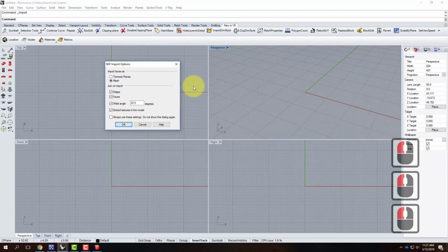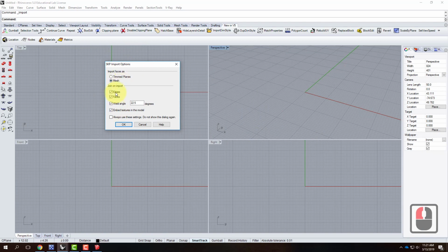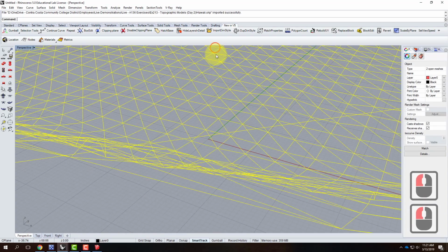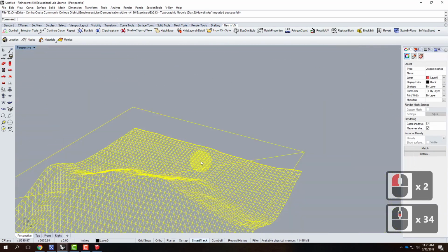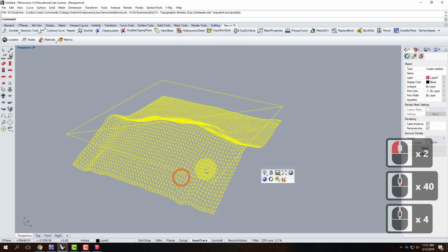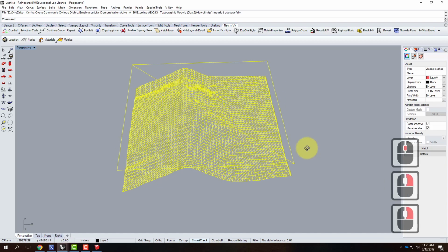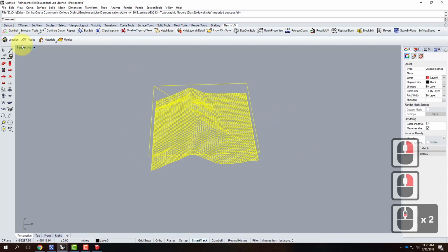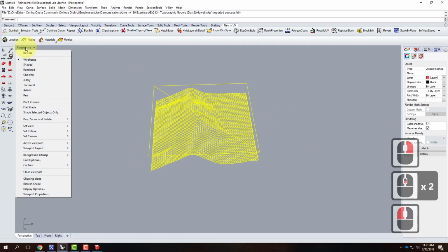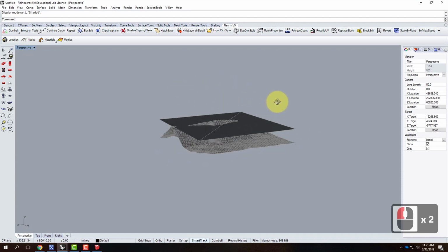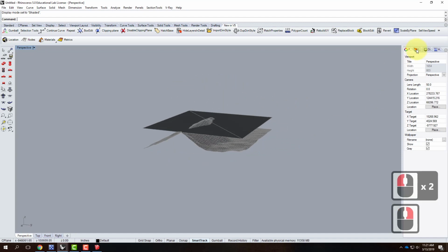These are the SketchUp import options here. I'm going to bring it in as a mesh. All the rest of the options are just fine by default. I'll go ahead and say OK. And that then brings in my SketchUp mesh file, which is right there. See, I go back and forth between SketchUp. I used middle mouse to orbit instead of right click to orbit. Anyway, I'm going to click on the little downward facing triangle in my view here and change to shaded just so that we can see the terrain. Yep, there's the terrain. It looks pretty good.